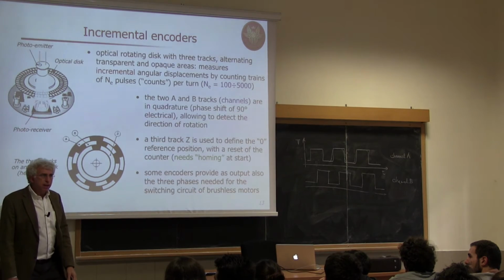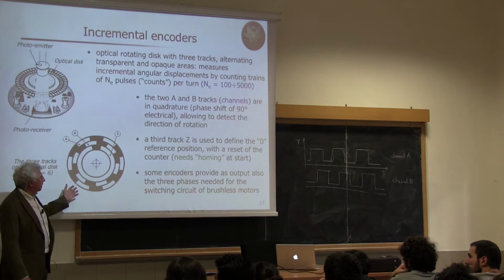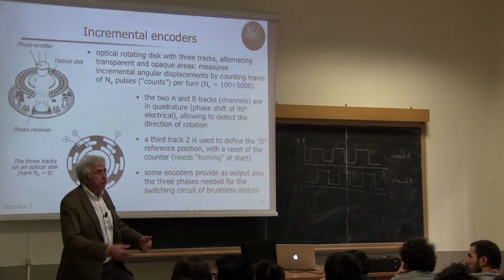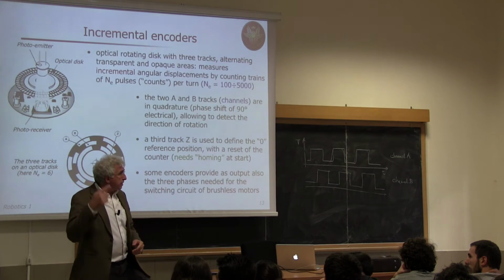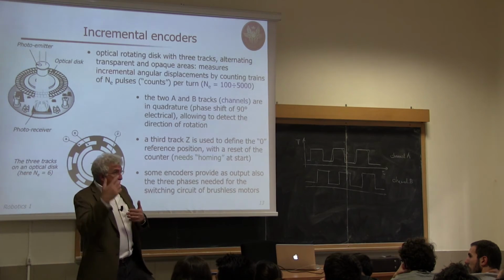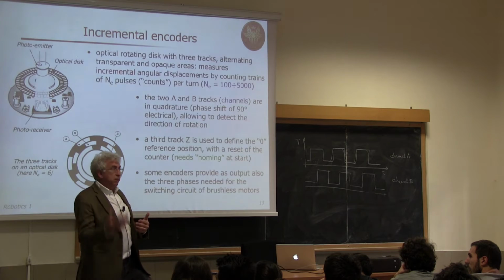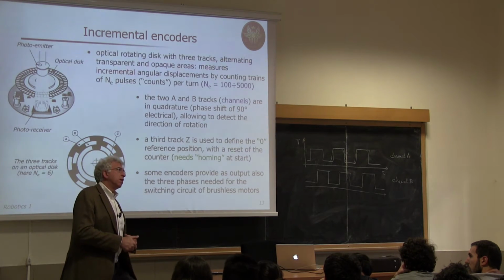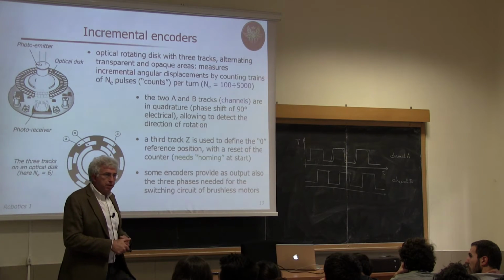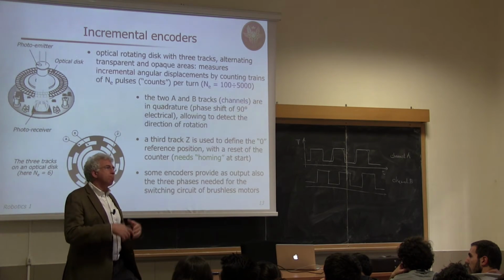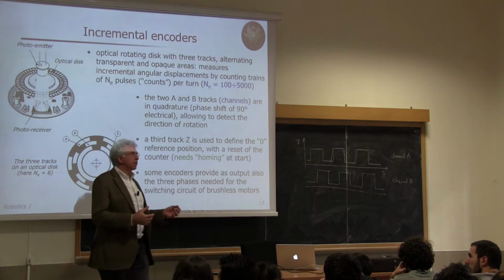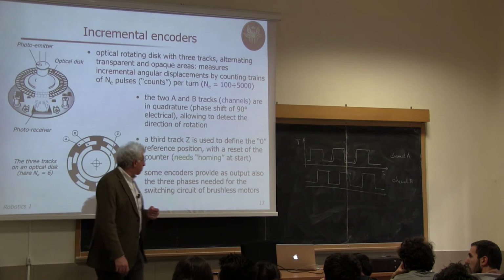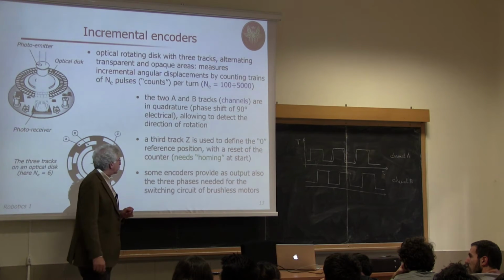Okay? So this, of course, depending on where this absolute incremental encoder is placed, typically on the motor side, you should always take into account that beyond the motor, you have a transmission element, you have a reduction of the number of turns per second. So the homing, so the zeroing operation should be made appropriately. We will comment on this now.